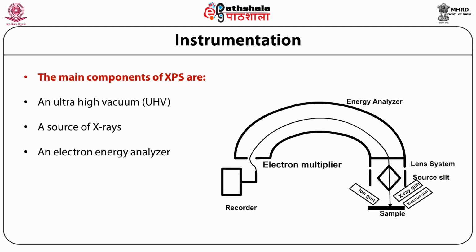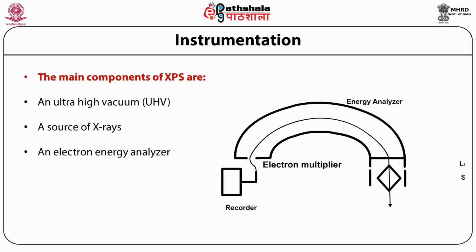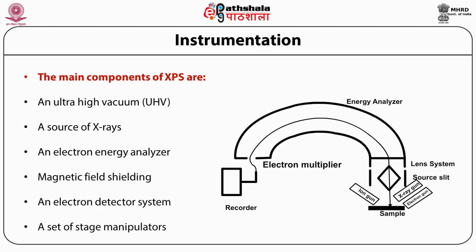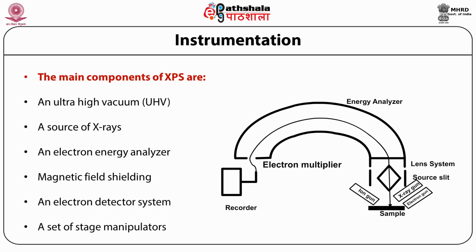The high vacuum chamber is commonly made from stainless steel, and joints of chamber parts are made from crushed copper gaskets. Ultra high vacuum can be achieved using diffusion pumps, sputtered ion pumps, or turbomolecular pumps. Magnetic shielding is also required for the chamber because the trajectory of signal electrons is also affected by magnetic field.